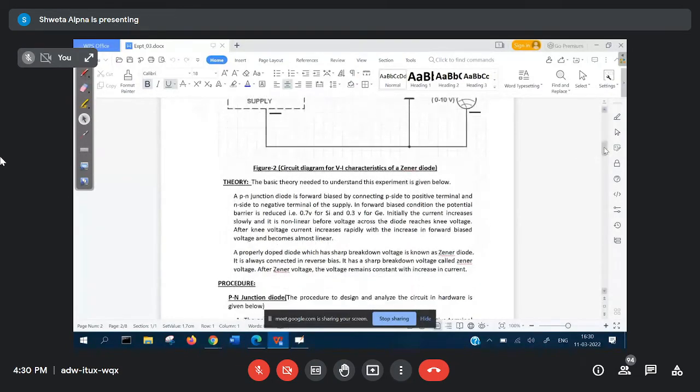So what is that characteristic? That characteristic is called as voltage regulator. So here you can see something is written: a properly doped diode which has sharp breakdown voltage is called as Zener diode. It is always connected in reverse biased. It has a sharp breakdown voltage called Zener voltage. After Zener voltage, the voltage remains constant with increase in current. So this is the behavior of the Zener diode.